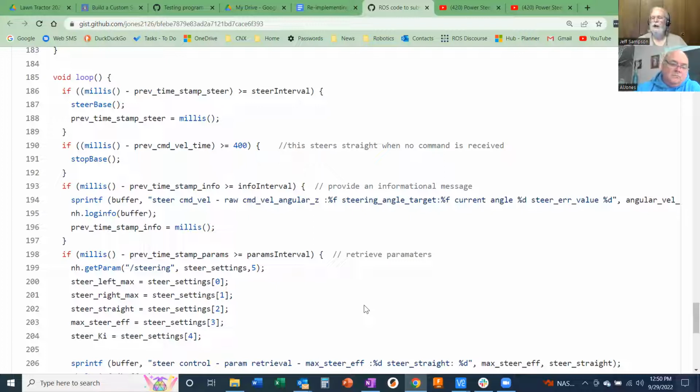So you had an actual serial port in the link somewhere, and when you go into your Arduino code and open serial at 9600 baud in setup, it's physically controlling that serial port on the board itself, and that's how fast it's going to output your characters. And you can set that quite high. I always set mine to 115.2K baud, which is about 10 times faster than 9600 baud.